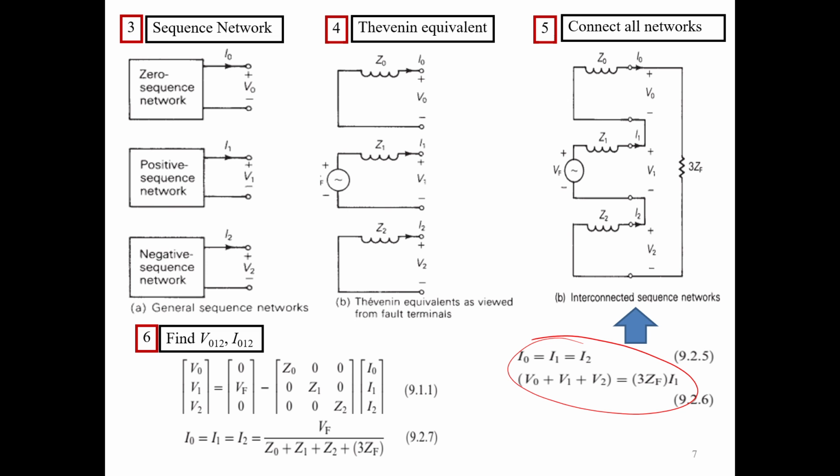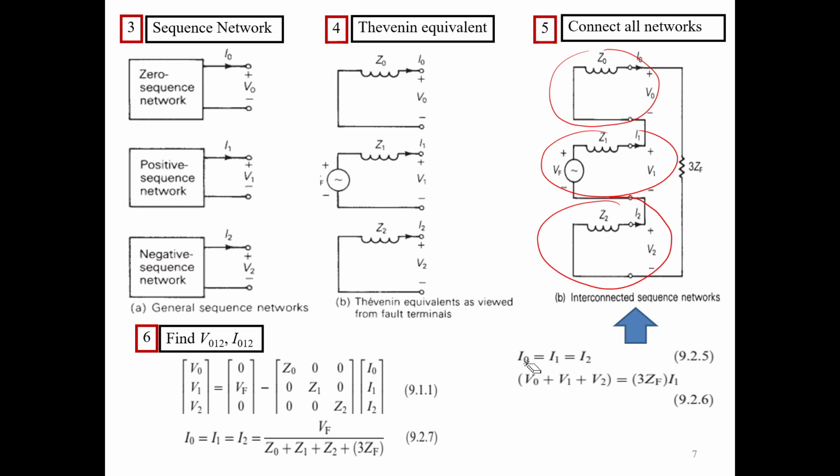As I mentioned earlier, you have the zero sequence network, the positive sequence, and the negative sequence, and these three networks share the same currents.